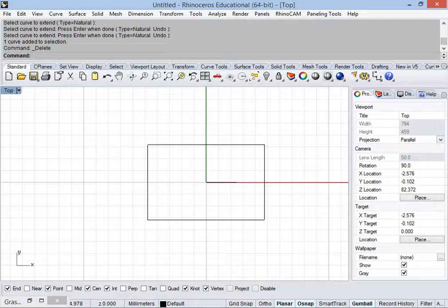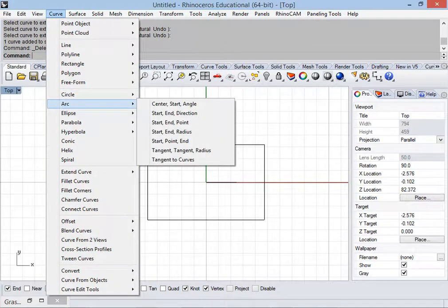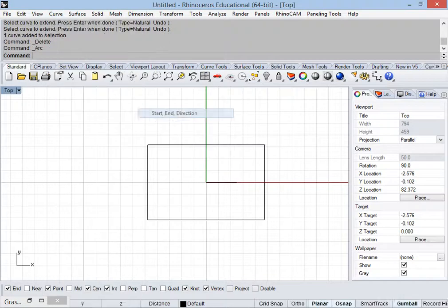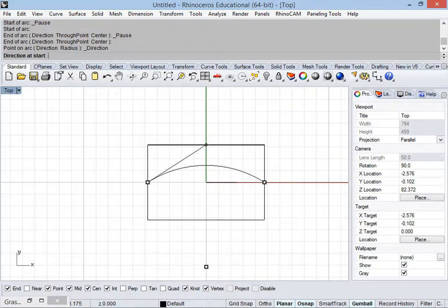So what can we start doing with this? We can start talking about arcs. Now when we get into curve geometry and arcs, this is right off of AutoCAD. If we were to type arc, it's sometimes too many steps to pick the one we want. So if I want start, end, direction, it's sometimes easier to do the pull down menu. Again, we might use different techniques. Snaps, O-snap, we want to make sure we're on. In this case, we want midpoint, start, end, direction, right? So we can decide what this means.